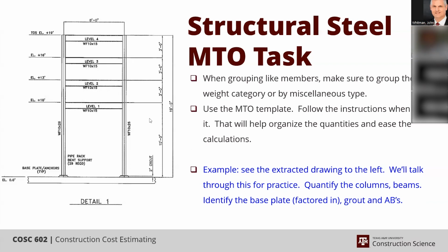So it's fairly straightforward. I think structural steel is one of the most straightforward. Where it becomes challenging is when you have a very busy drawing, because pipe racks can be taken off very quickly, just like they can be erected. Open structures are a little more complicated to erect, because there are a lot of members interacting with each other, and they're also a little more difficult to take off because there are a lot of members involved, of various types and sizes.